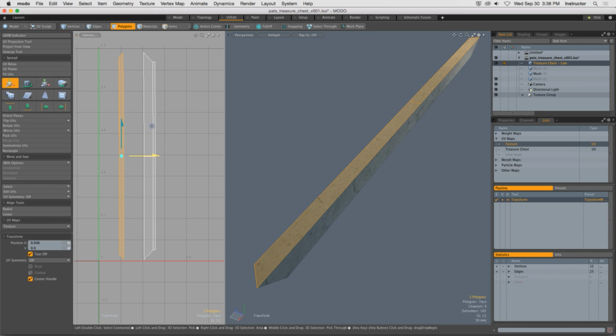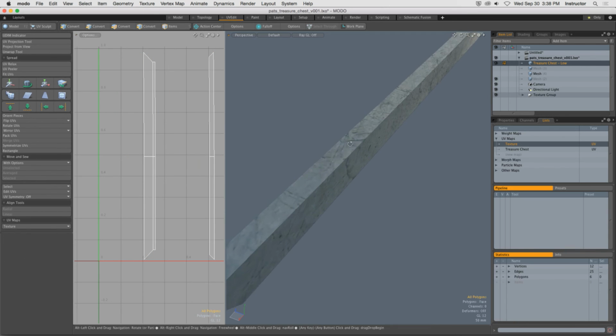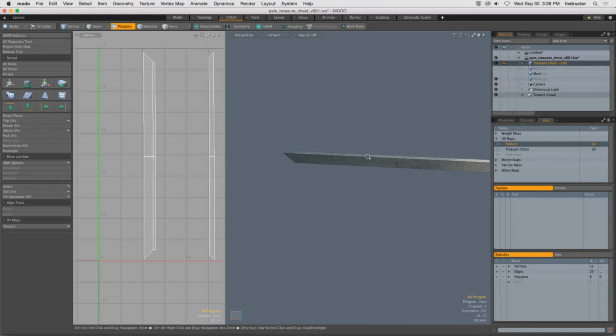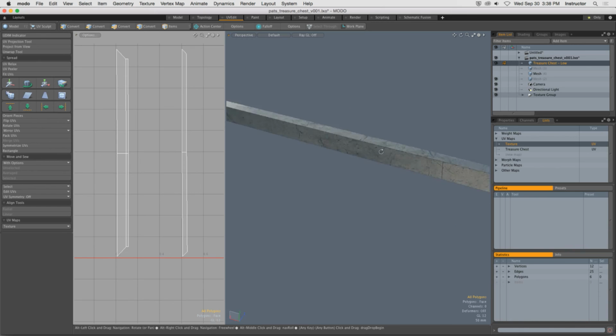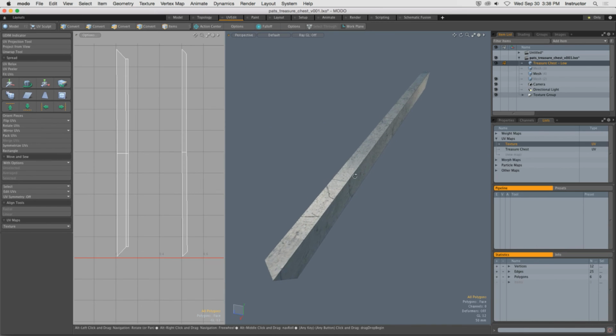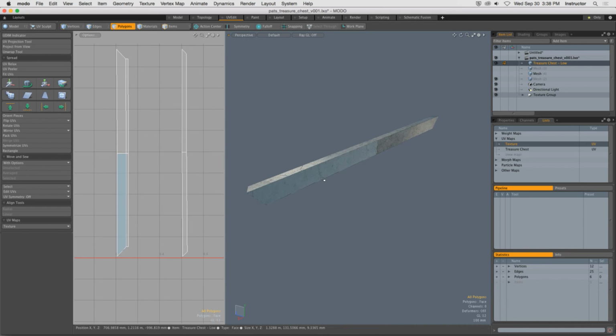And I'm going to put this in a radically different area, okay? And now, on this particular texture, we'll really break it, because you really can't notice, but if I was to, yeah, there we go. Now, if you look visually at it, it looks like two pieces of metal, right? Wherever we create a seam, that new UV island is going to be in a different part of the texture, and it's not going to look as though it's one cohesive piece, okay? Something that we want to strive to avoid as much as we can, okay?